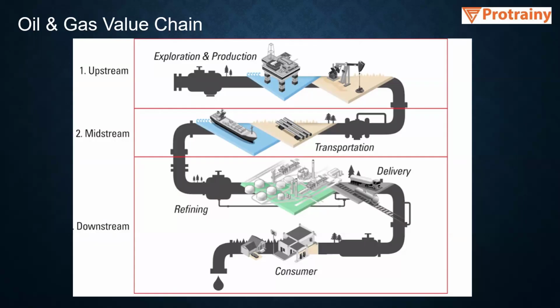So that is upstream, from where you are getting the crude oil or the crude gas for further processing. Then midstream. Once that crude oil or natural gas has been recovered in the upstream, it needs to be transported to the downstream. So the transportation medium is considered in the midstream, which includes, for the case of LNG, LNG tanks and vessels over the ship, and then cross country pipelines that will be transporting the crude oil from one place to another place, to the refinery for processing.